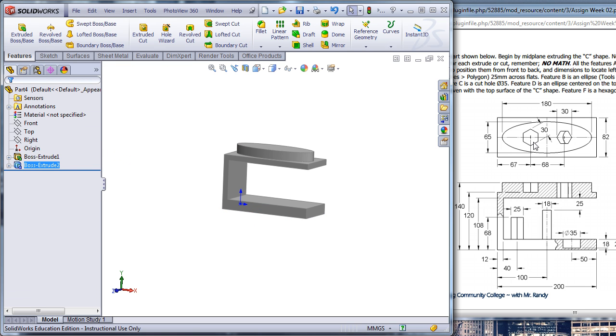All right, I have 2 hexagons on this top surface, but if I look in the front view, in the section, notice this hexagon doesn't have a depth cut. It's cut even with this surface right here, this 120 millimeter surface. We've already used that dimension. I can't use it again when I cut this one. I've got to cut it up to this surface. This hexagon cuts through to this edge. So I cannot sketch these together. I can't put them in the same sketch because they have different cut depths. Okay? Can only do them in the same sketch if they're cut the same way.